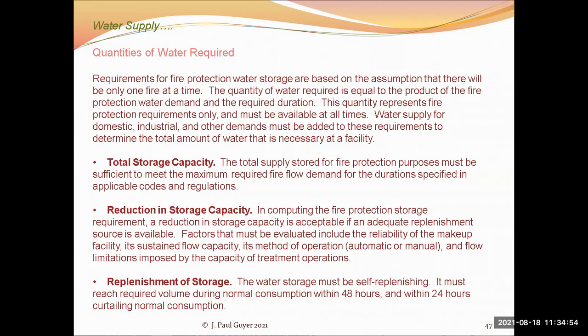And typically you go to a catalog and pick out the sprinkler head that you're going to use. And typically the manufacturer will say, well, if you provide water at a pressure of at least 20 PSI at this head, it will distribute so many GPM per square foot over such and such an area, 200, 300 square feet, something like that.